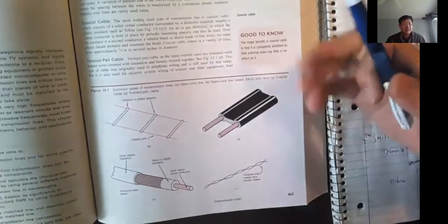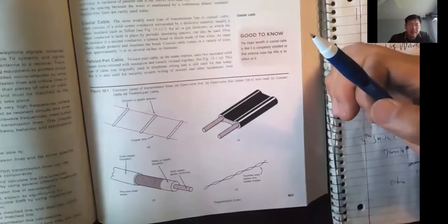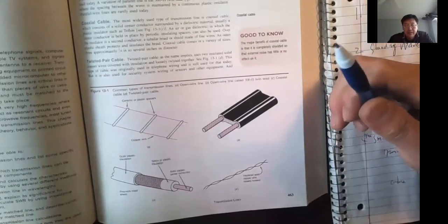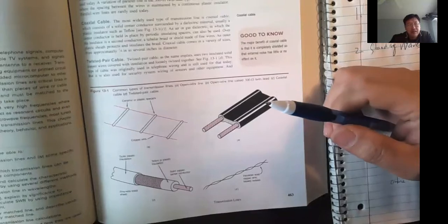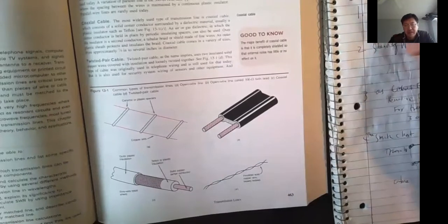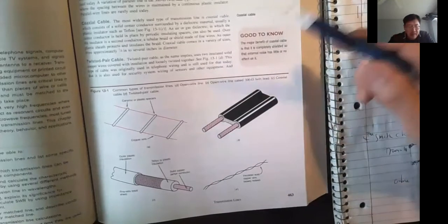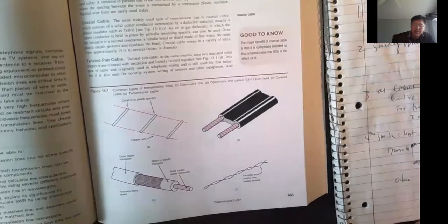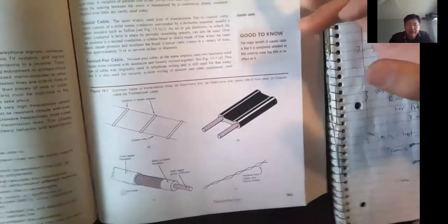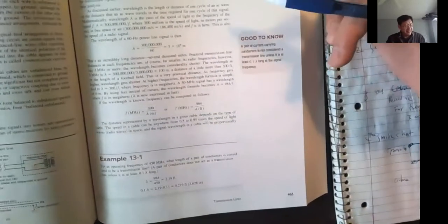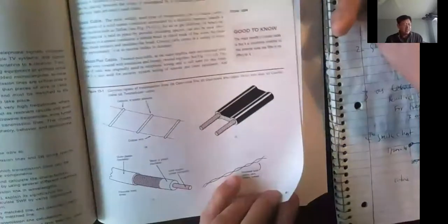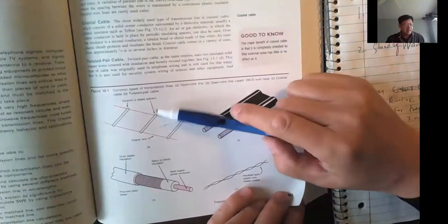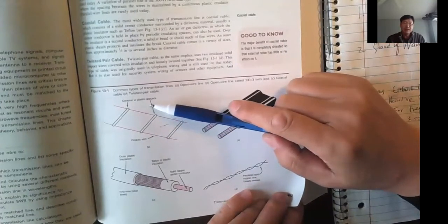For a conductor 1 foot long, we really don't worry about the resistance, because the resistance is extremely low. We're not talking about a conductor 100 miles long or 100 feet. Then you start to care about resistance. Now, with a short distance, the resistance is not what we care about. What we care about instead is the inductance and the capacitance. The inductance and the capacitance make this transmission line a reactive wire.